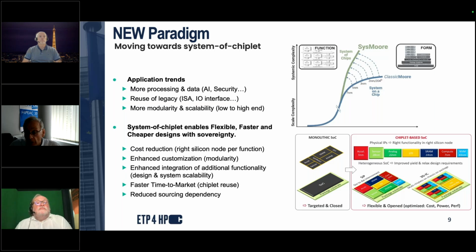And this approach of a chiplet on interposer has several advantages. The first one is, when you make a monolithic, big die composed of processing, memory, and IOs, the technology is not optimized for its functionality. The technology for processing is not exactly the same as for memory or for IOs. So that means that you have an overall average performance on your monolithic die.